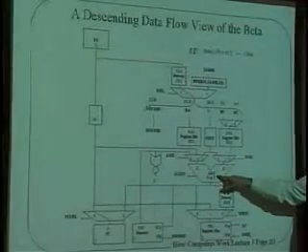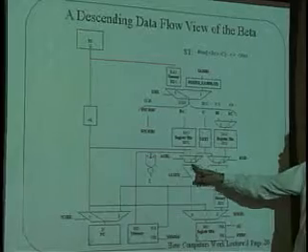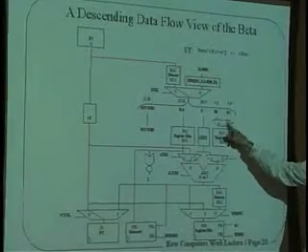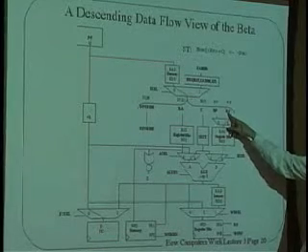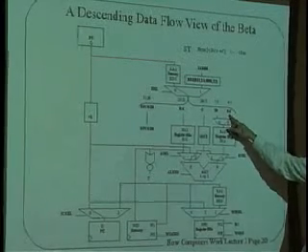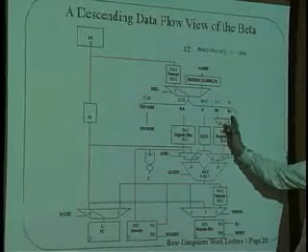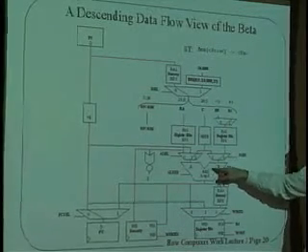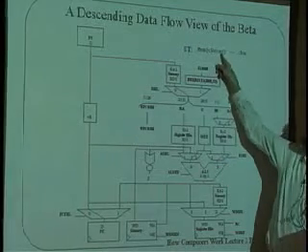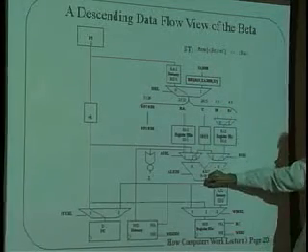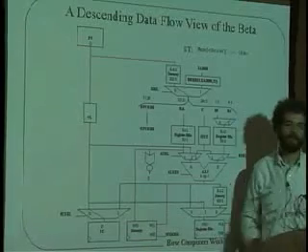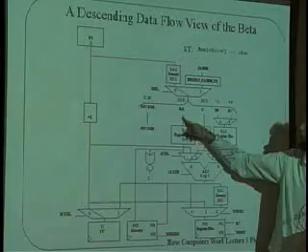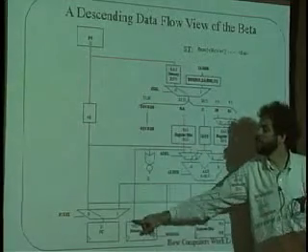And what location are we going to write? We're going to write the constant C plus the contents of register RC. So RC is going to get chosen here. It's going to get looked up, going to get fed into here, and will be added to C, just like it says right up here. And that sum will be used as a pointer into the big slow memory over here, and that will be the location that we write the data, which is the contents of RA that comes out here.